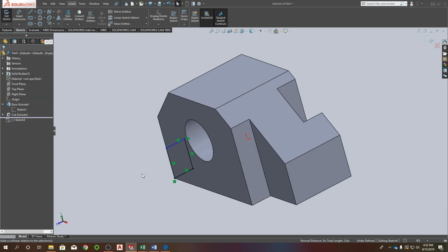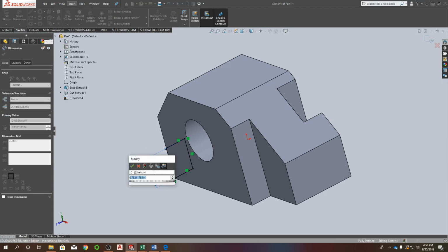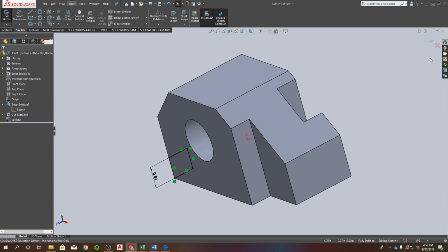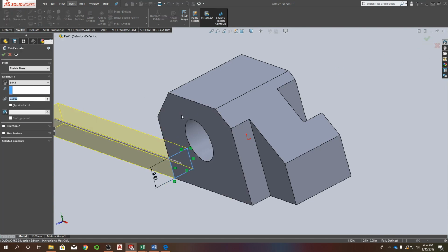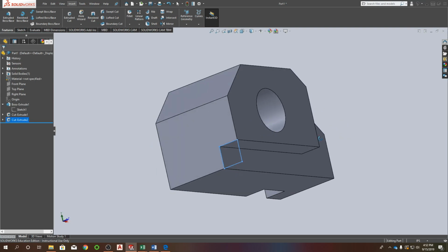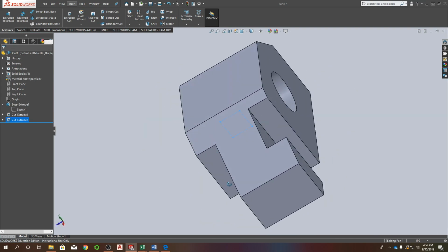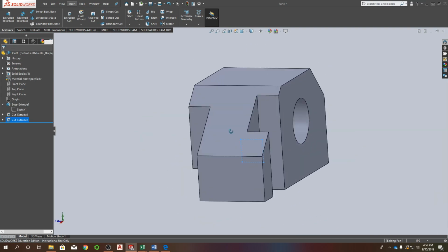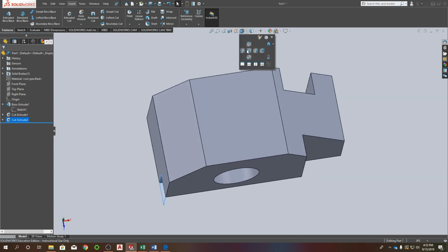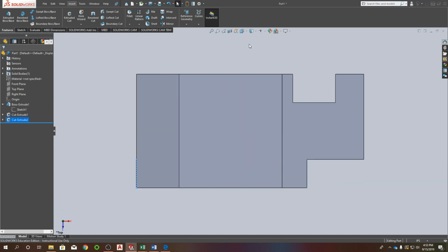And now all I have to do is set the height there, and that is 0.5. Check. Exit the sketch, flip the direction, and set it to through wall. And there's that part. So once holding down the middle mouse button, I can rotate this around. I can go to here and set it to top.